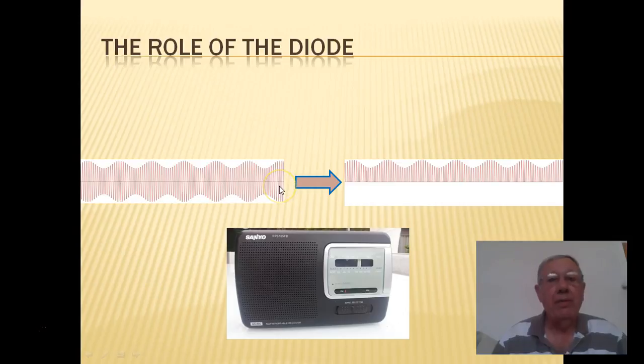So the effect of that is to cut out the bottom half of this wave. So you can see there that this illustrates the electrons moving in one direction, and that part moving backwards, if you like, is cut out. So the electrons just go along like this. They can only flow in one direction. So we've got, in fact, what we might call a DC, or a direct current.